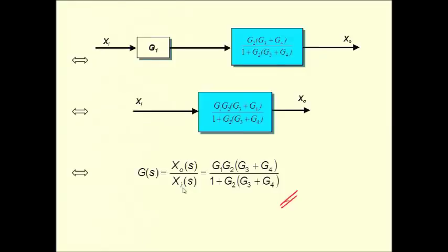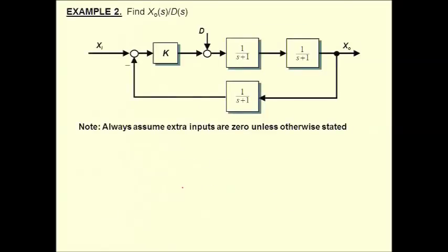Questions? All right, next step, a little bit more difficult. This block diagram does have transfer functions in it. K alone is just a gain in this case. I guess it could be a transfer function, but we're going to treat it as a gain. It's just a number that we put in here, like 2 or 5 or 2.6. And what's involved? There's a summing junction with one negative signal. Remember, any signal that's not labeled is positive, like these two are both positive.